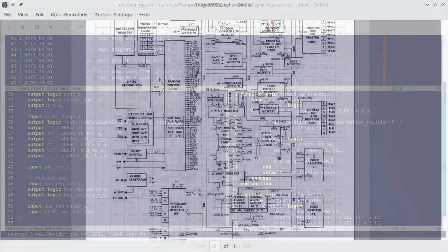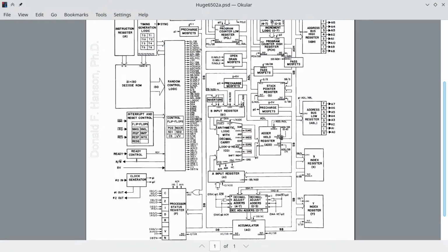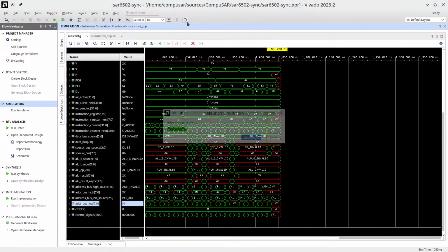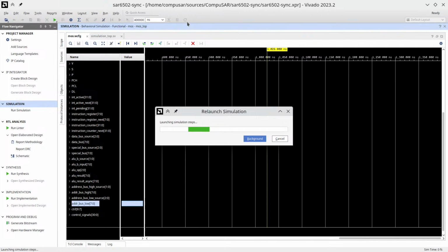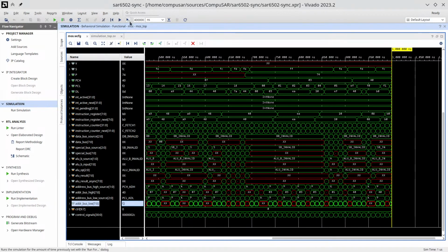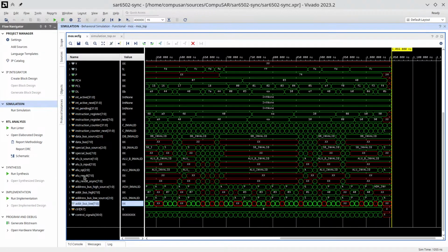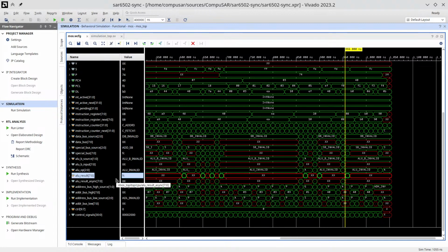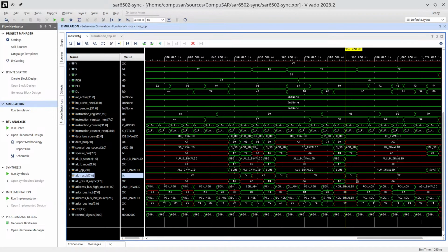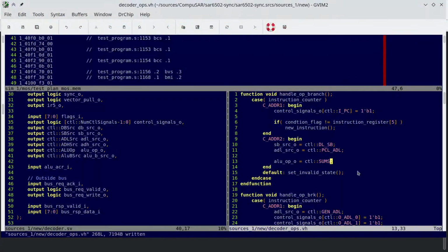And that is going to latch the result of the addition here, but it will only actually appear on the next cycle. So if we execute the code, of course after compiling it, we see that ALU result gets FC, but it gets it in the cycle after we set the ALU op to sums, which means that for this cycle, we're done.